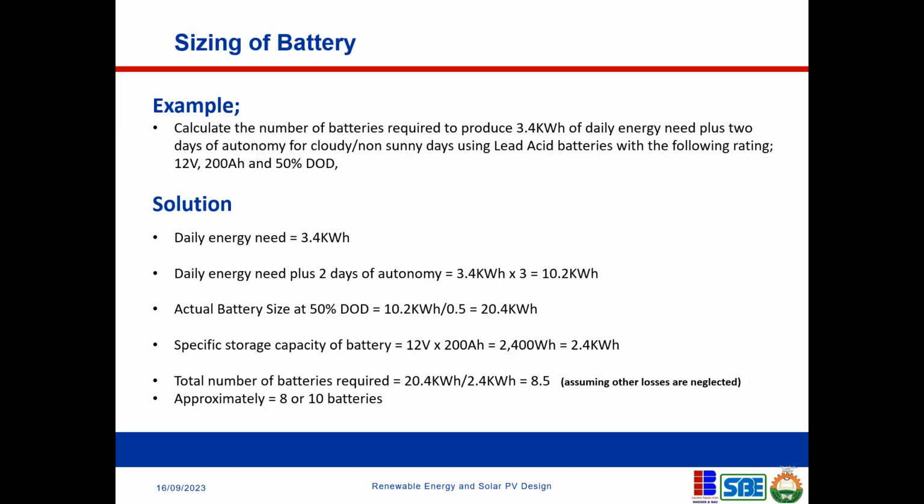Unless your inverter is a 12-volt inverter, then yes, you can use 9 batteries, because you can feed the individual voltage from the batteries directly to the inverter, in which case you are just connecting in parallel. We are still going to come to series and parallel connection, where I will explain more on this. If it's still not clear to you, just hold on.